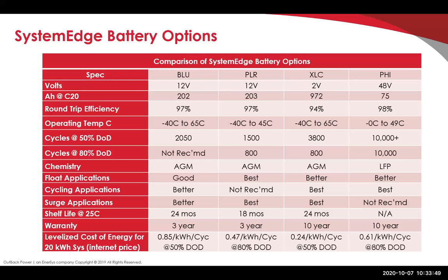So temperature, if you can keep the batteries in a place that's maybe not air conditioned, but I've even seen people put some kind of air conditioning, with the thermostat set really high, like 85, 90 degrees, just so it doesn't get too hot in there. It depends on the batteries. You can look at the operating temperature.